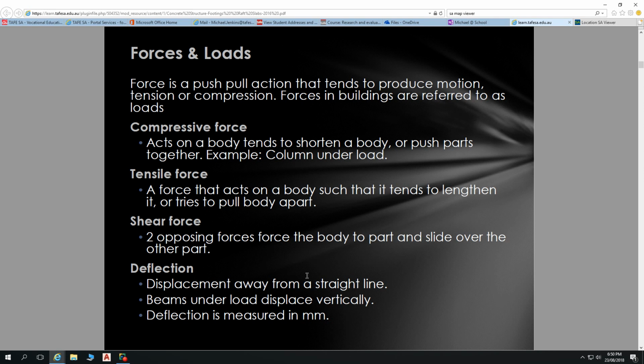But also, sometimes we're going to have elements that will deflect, and we have to hide them away in the building as well. So that's things like lintels and so on in wall frames. These are the lintels happening up here, above our windows there. Those lintels are going to deflect to a degree, but that lintel is going to be hidden away in that wall frame.